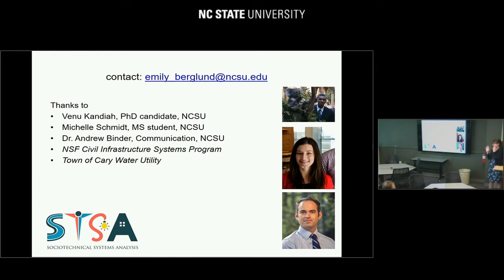Here with the expansion plans, we could just import that as data. We also coupled it with pipe network models. EPANet models flows through pipe networks, and so we coupled it with that to calculate impacts, like how much water is left in your tank and what's the pressure at different points in your network. I didn't talk about that today. And for the CA? The CA we also did in AnyLogic. It can do CA, ABM, and discrete event modeling. Thank you. Yeah.